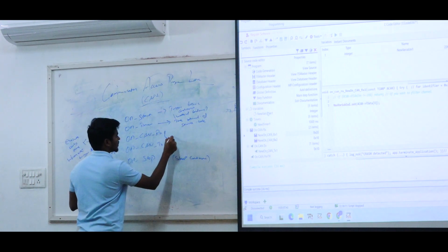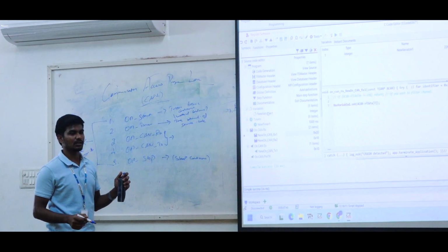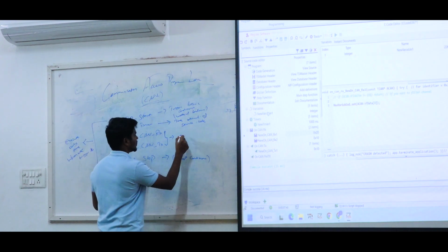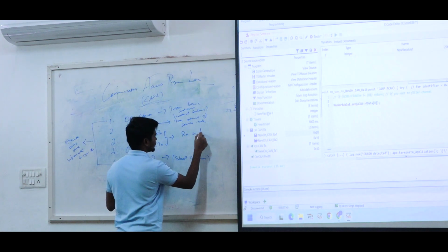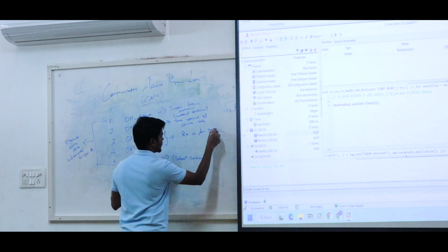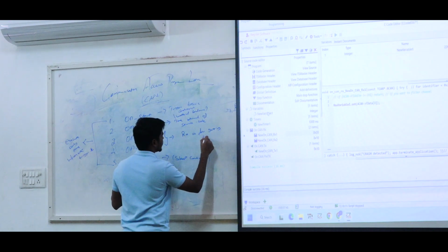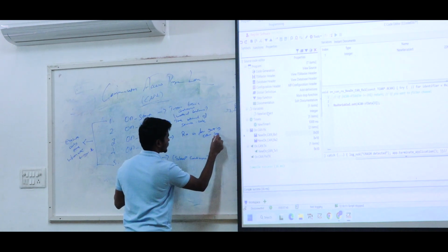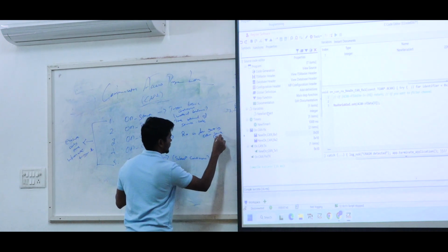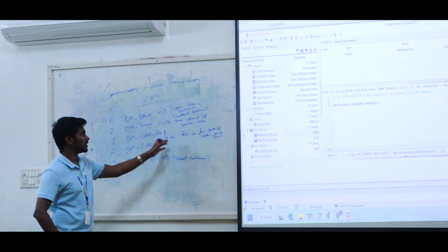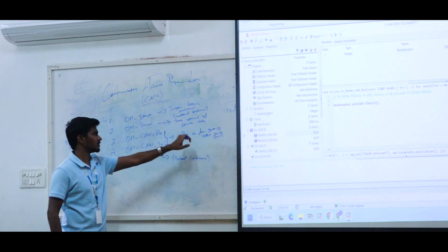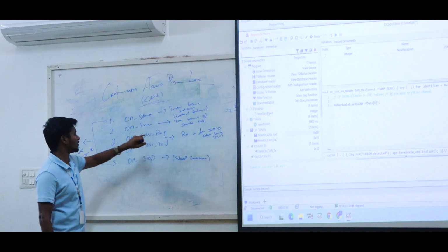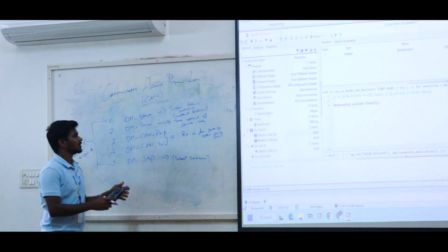So on RX and then on TX are used based on conditions. RX is for getting data from another source, like an ECU. Whatever values the other ECUs are transmitting, we are able to receive here with the help of the on RX event.